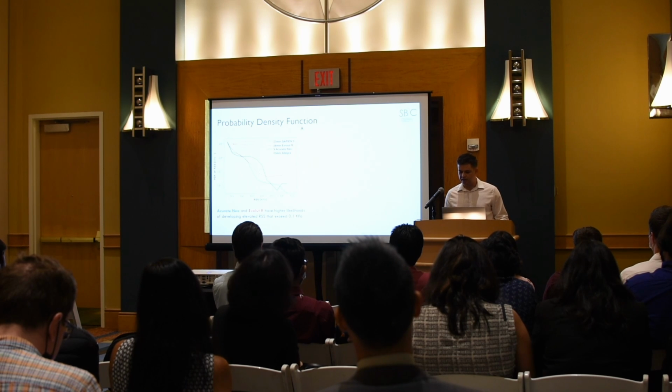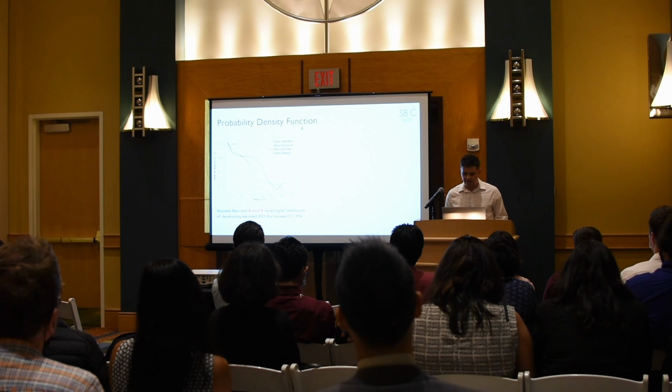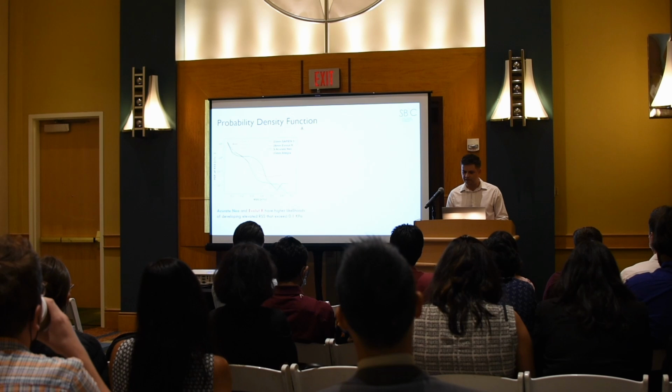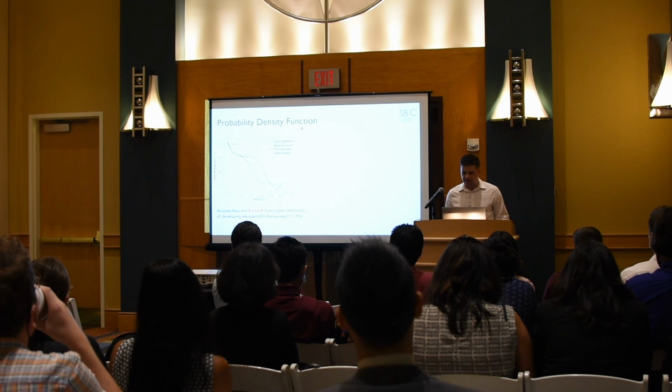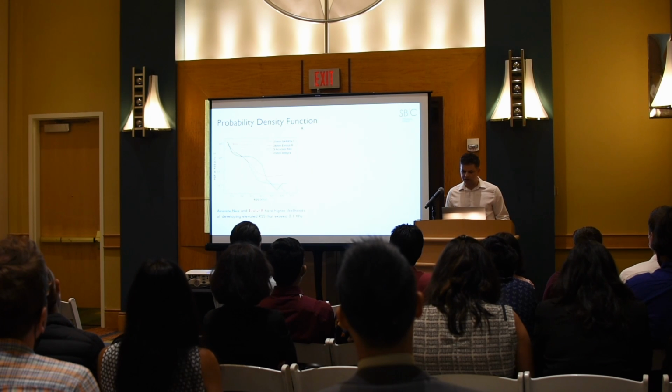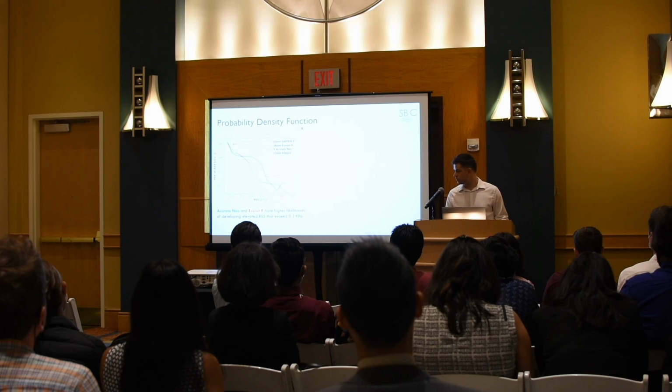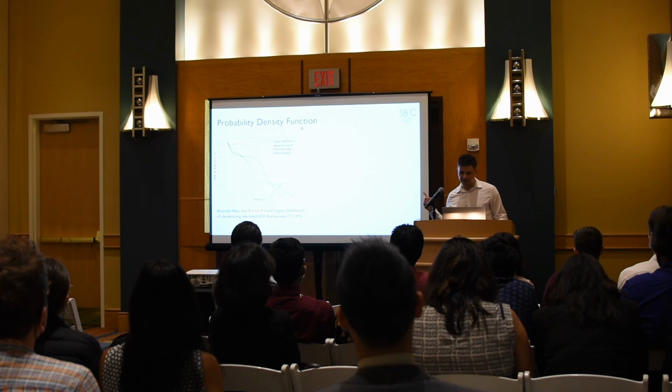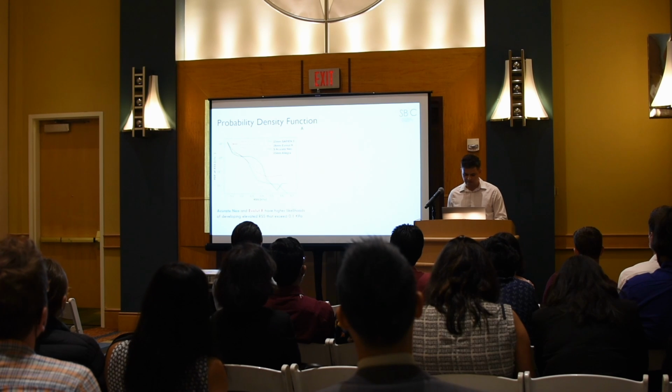The Allegra shows the minimal range of Reynolds shear stress, which is up to 320 pascals, followed by Evolut, which is 600 pascals, and then Accurate and Sapien. In the literature, it is reported that any value exceeding 100 pascals can be associated with blood damage. The Sapien 3, Accurate Neo and Allegra show equal distribution for Reynolds shear stress less than 100 pascals, but the Evolut shows higher values.